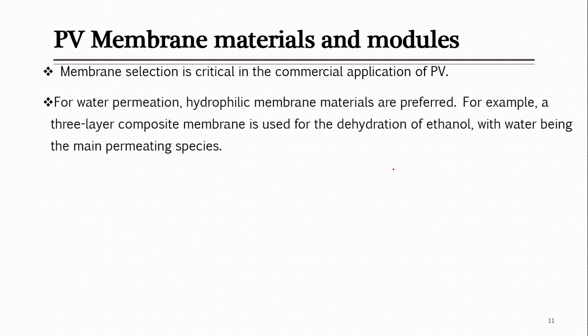Let's look at this. For example, for water permeation, hydrophilic membrane materials are preferred. Why hydrophilic? Because if they attract water in large amounts, if the material you are using is attractive for water, more water will be attracted, and better separation can take place for this